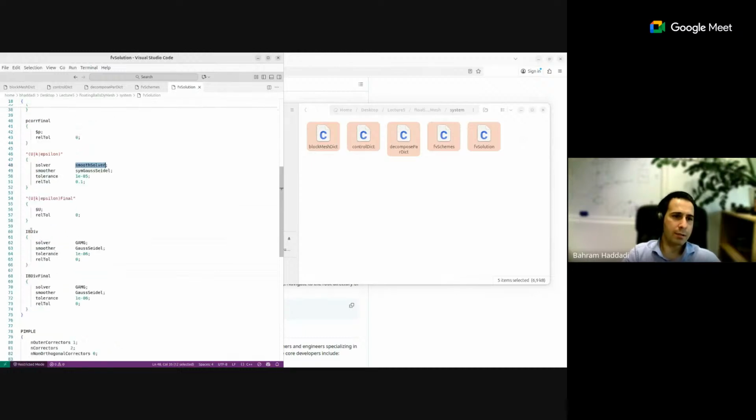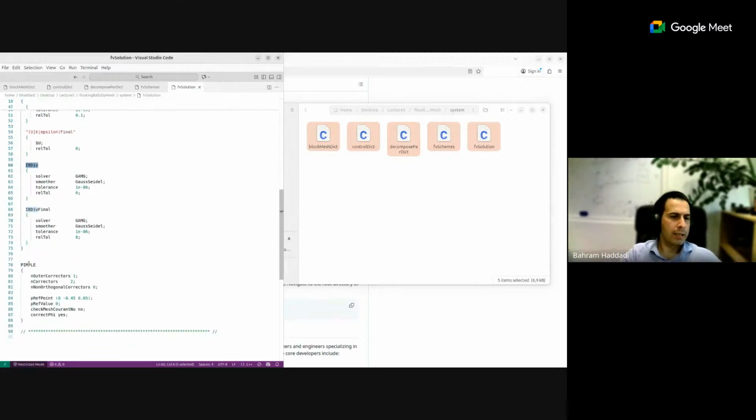And then we also need another solver for the immersed boundary divergence, because the approach and method that we have built into the current version of the resolved solver is an immersed boundary, a volume penalty immersed boundary approach. This is for calculation of the divergence field, which gets transported in there. Good, and then the typical pressure-velocity coupling is done using PIMPLE, and since we have the number of outer correctors set to 1, that means that basically it's working like PISO. Again, to know more about that, feel free to stop by next week.